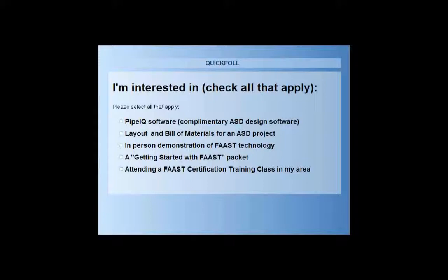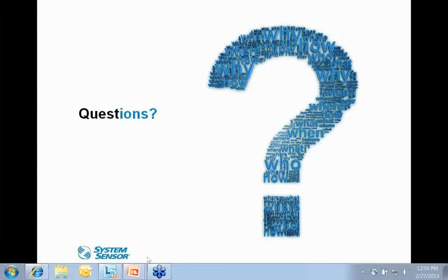Okay. Maybe the final question here, how can this system be attached to a building automation system? Currently we provide the Ethernet port that will tie into the IP infrastructure. You would get an IP address like a PC would on that infrastructure. You also have the SLC loop version of connecting to the fire system, and then, as I mentioned, in the near future, we are going to have Modbus capabilities on the Ethernet port, which will then communicate Modbus to the building solution infrastructure.